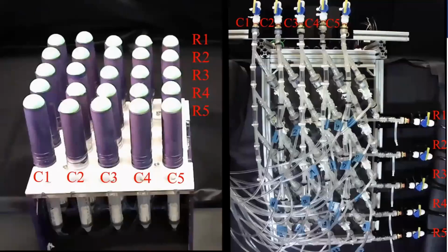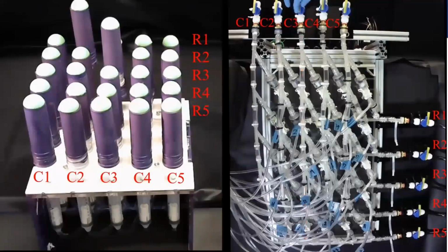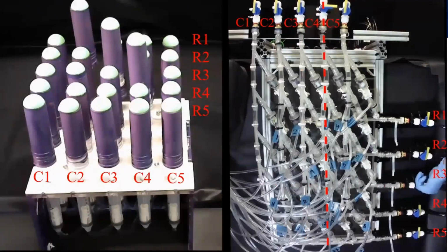This video shows the control of an array of actuators using our fluidic matrix circuit. A row of fluidic logic modules connected to one inlet manifold within the fluidic matrix circuit is turned on, and then the specific fluidic logic modules within the row were addressed by switching the states of the electromechanical valves in the corresponding column. Hence, controlling the actuator involves controlling the state of the corresponding row and column, as shown in this video.